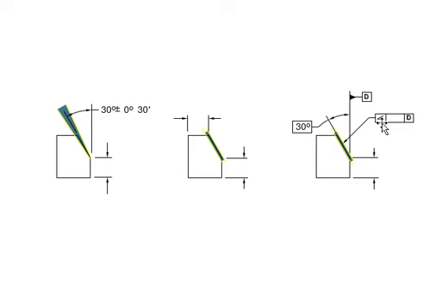So we're going to use our angularity symbol, and then our datum. We have only a single datum on this reference plane, which is related to this surface right there. So we call that the datum reference D. Of course, we're going to throw in all of the necessary tolerance material right in here. So that's a 30 degree plus or minus 0 degree 30 minute polar tolerance zone, controlling that angularity.